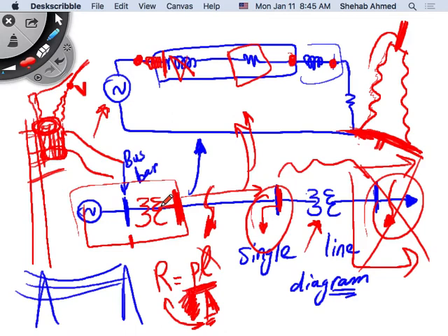If I want to push that same current the transmission line is pushing, if the same current coming out of the generator is going to have to go through that transmission line at the same voltage level, and the generator is a lot smaller in this case, the luxury I have in the transmission line is I can space the conductors a few meters apart. How about in the generator?